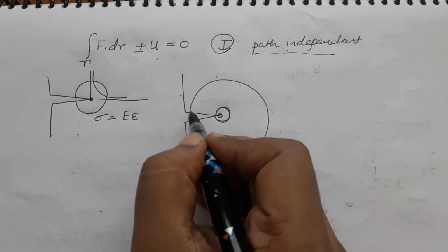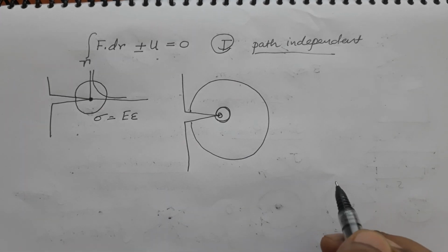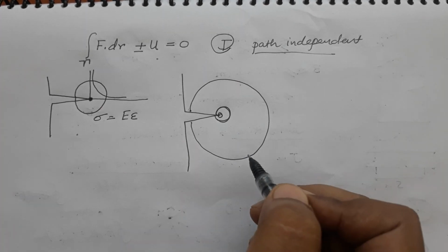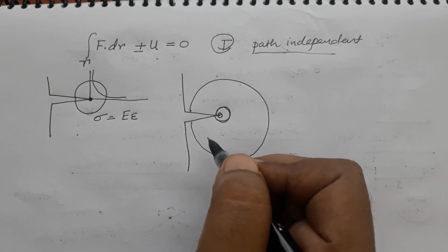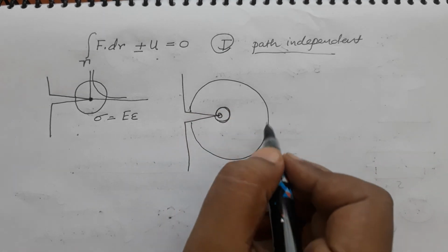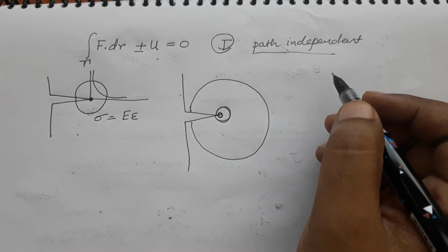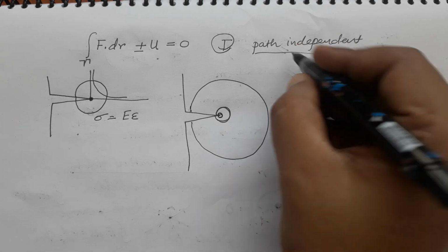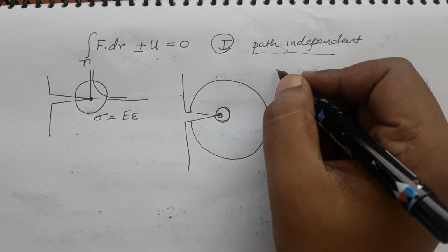And so I take the integration at a remote location where I know for sure what is happening, where I can measure the strain values, where I can measure what the force is, what the stresses are. And if I know that value, I also know this value, because it is path independent, and that is what makes it so beautiful to use this idea in fracture toughness.